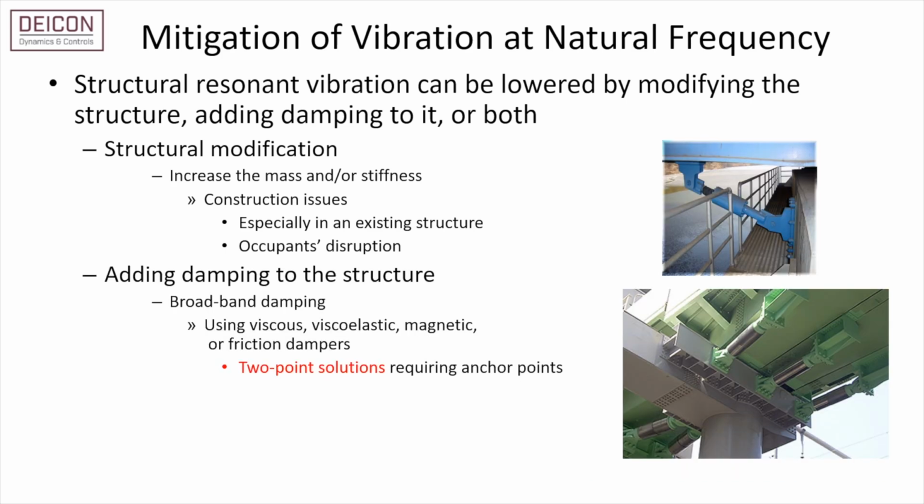Damping, on the contrary, aims to dissipate vibration energy within a structure. This involves integrating specific damping devices into the structure's composition. Various mechanisms such as viscous, viscoelastic, magnetic, and friction are employed in making dampers. Dampers are two-point devices. They not only connect to the vibrating structure at one end, but also require anchoring to an abutment at their other end for effective operation.